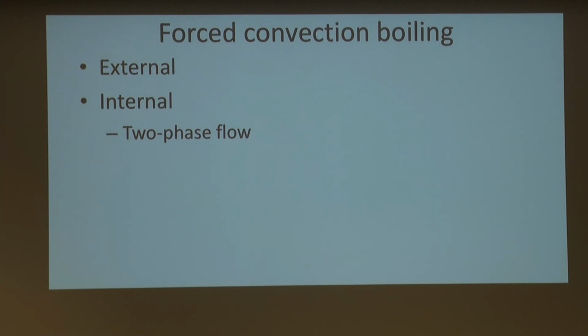So this curve we have here, you can move it. If you wanted to enhance boiling, there are special systems. In the book, they have a whole section in which you can have places that help you nucleate the bubbles, right? Again, all those are relative subtleties. What matters is you have this curve in which you have a behavior that is not intuitive.